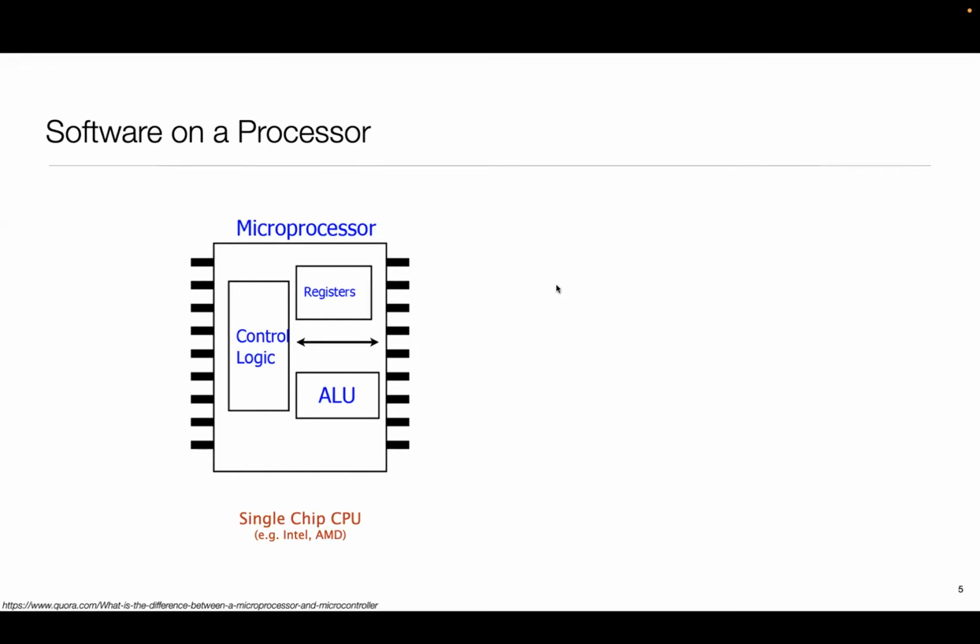So anytime you go outside, there you are paying a penalty for that. And moreover, the rate at which the signal travels over a wire is affected by its resistance and capacitance as well. So you want to keep information close, and therefore registers are implemented by a particular type of logic primitive so that it's kept on chip close to it. And a lot of games you can play.